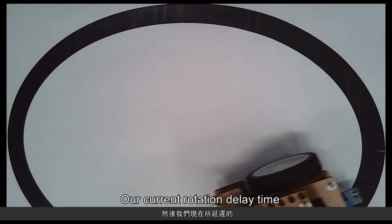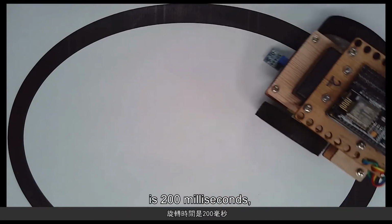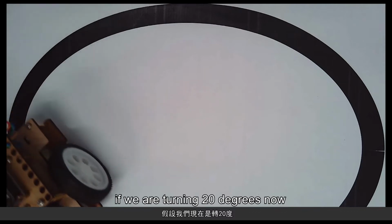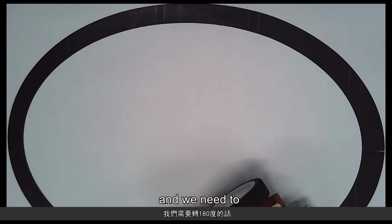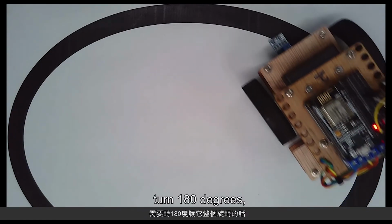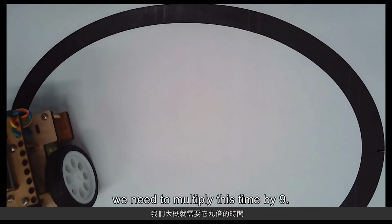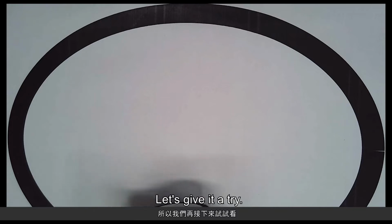Our current rotation delay time is 200 milliseconds. So we can roughly estimate if we are turning 20 degrees now, and we need to turn 180 degrees, we need to multiply this time by 9. Let's give it a try.